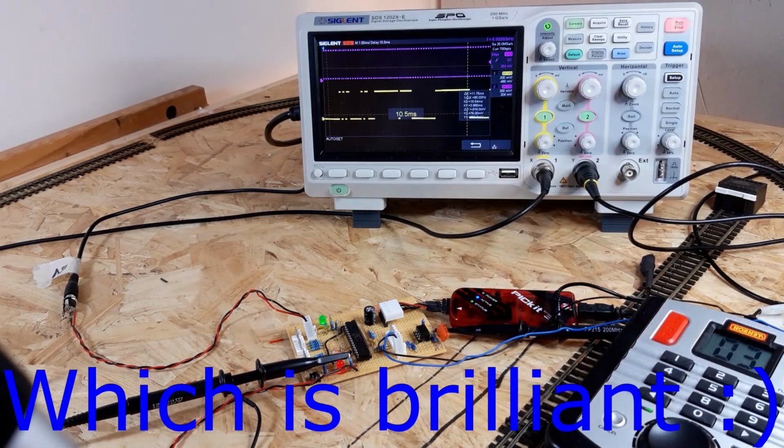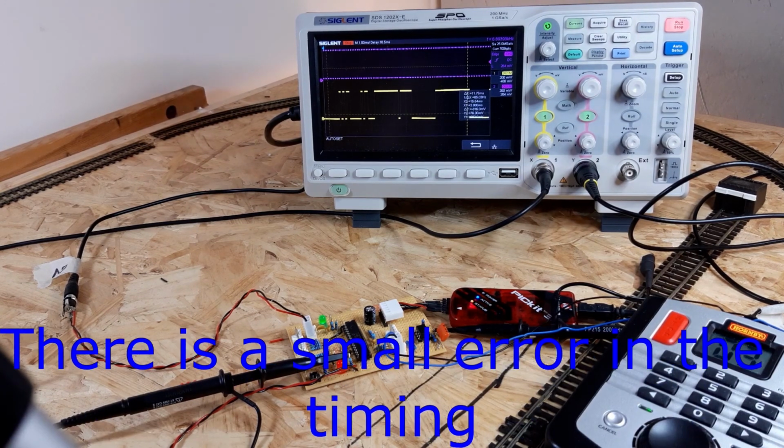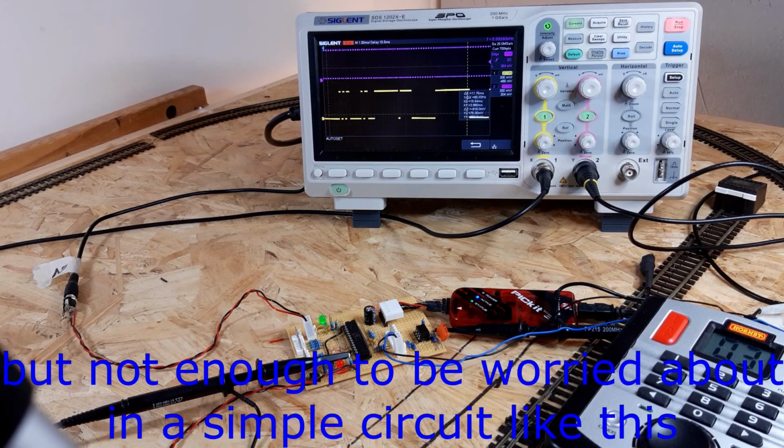Which is brilliant. What we actually found, because we're not using a crystal oscillator on the microprocessor, is that there could be errors in the frequency at which it's running, which will affect the timing period. But we did have a look at that, and it was a small error in the timing period, but not enough for a simple circuit like this to be worried about.